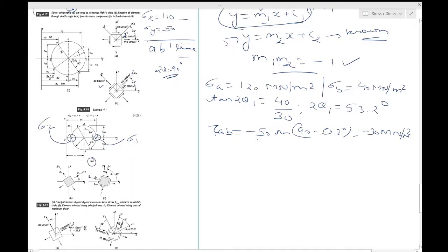These are normal stresses, clearly, because they lie on the sigma axis. And another thing is that there is no shear stress; tau is 0 at both of these points. So the coordinates are actually sigma 1 comma 0 and sigma 2 comma 0. Somewhere over here the same is not true; here you will have both sigma and tau.